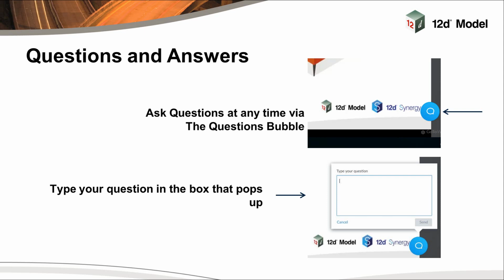I don't know the answer to that question. I've never had to do it. When you have a frame or place a frame in the preview, you can type in a model name in that parameter. So it actually creates in 12D a model that you can turn on in any 12D model plan view that dynamically has that rectangular shape and the position of that frame.